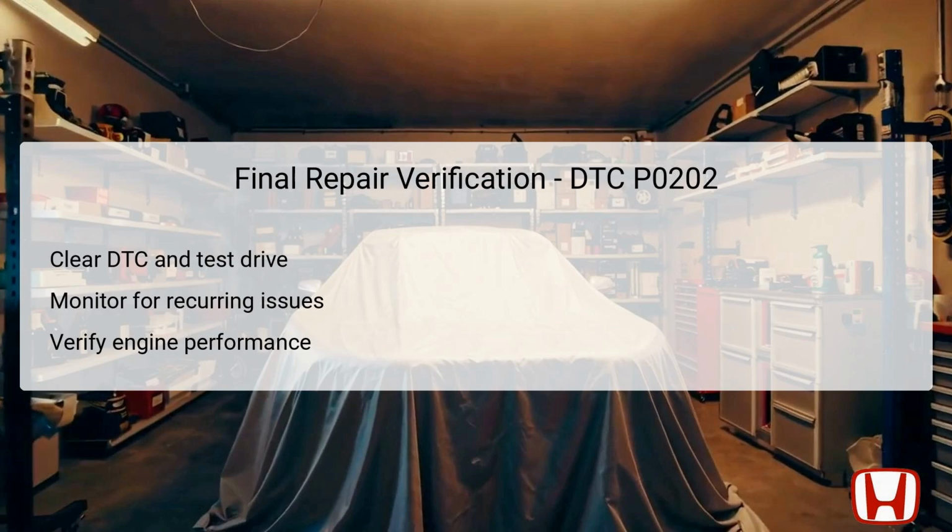After completing all necessary repairs for the DTC P0202 malfunction, it is essential to perform a final verification process to ensure that the issue has been fully resolved. Start by clearing the DTC using the HDS and conduct a test drive to observe how the vehicle behaves under normal operating conditions. This process allows you to monitor whether the DTC resurfaces, which would indicate that the initial repairs were not effective or that another underlying issue exists.